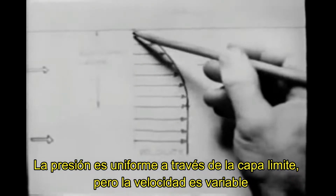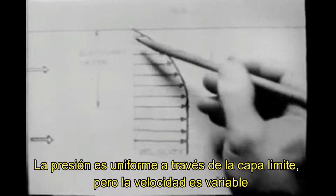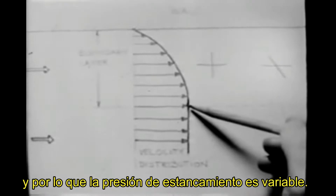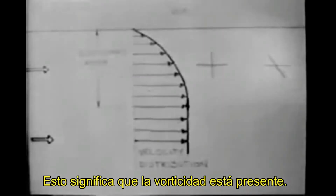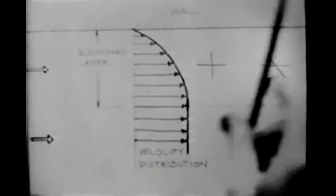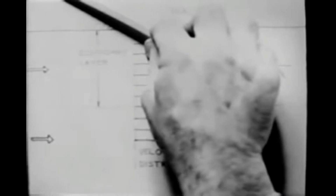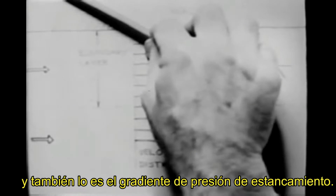The pressure is uniform across the boundary layer, but the velocity is variable, and so the stagnation pressure is variable. This means that vorticity is present. The velocity gradient is strongest near the wall, and so is the gradient of stagnation pressure.